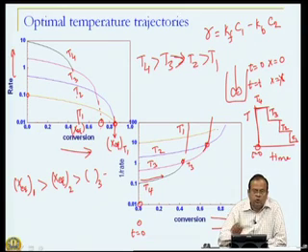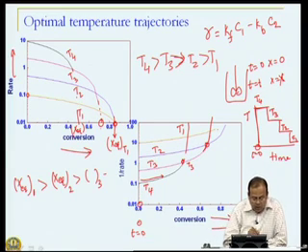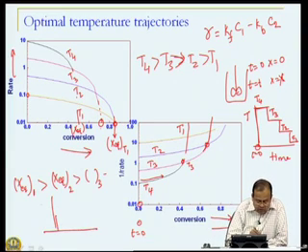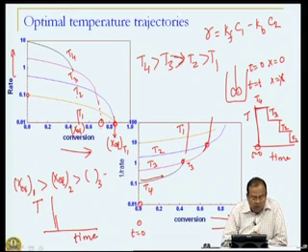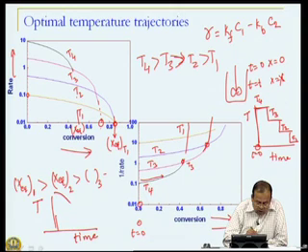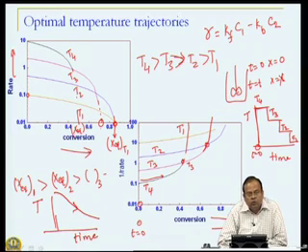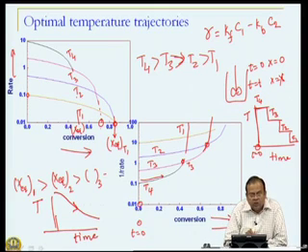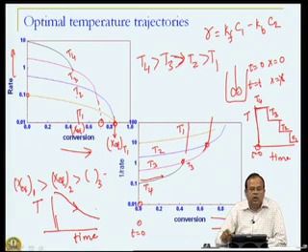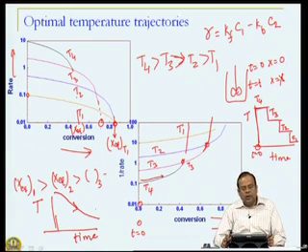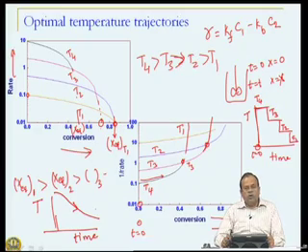This is, suppose I were to do it in a stepwise manner, but I can now extend this, saying that for an exothermic reaction in a batch reactor, my temperature should decrease from a high value to a low value as the reaction proceeds. The counterpart of this in a plug flow reactor is that my temperature should decrease along the length of the reactor. How do we do that? We will try to see in subsequent classes. So, we will stop here for the day.